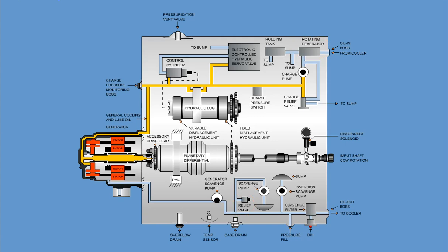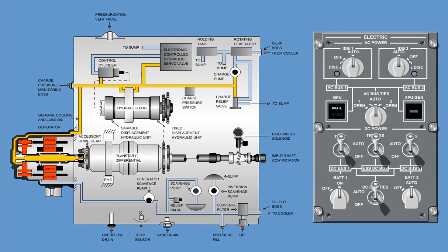The bypassing uncooled oil will cause the IDG oil temperature to increase and may cause the amber fault light in the IDG control panel switch to illuminate. The scavenge relief valve also opens during cold start conditions because of the high pressure created by high oil viscosity in the external circuit.